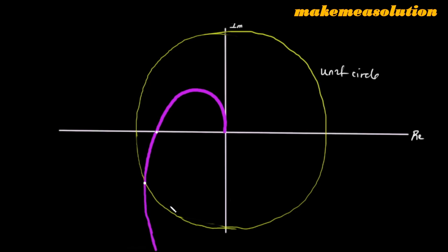Remember that we got the Nyquist plot by plotting what we call a polar plot. A polar plot is magnitude versus phase, and it is usually in the form of radial lines. The radial lines are the magnitude, then the phase tells me the direction that the radial line is pointing to.